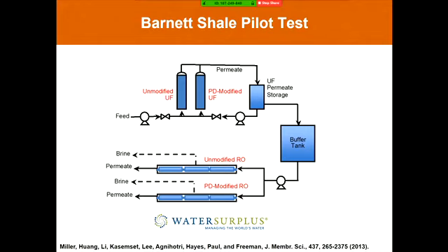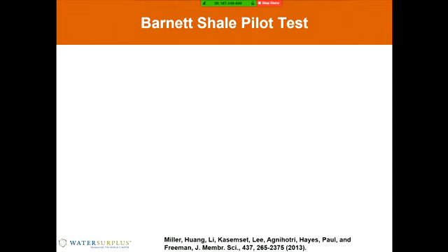We also had reverse osmosis on this material after the UF stage to remove salt. I won't talk about those results today due to lack of time, but basically once the ultrafiltration membranes had removed all of the oil and particulates, the RO membrane essentially didn't foul over the duration of these pilot tests.